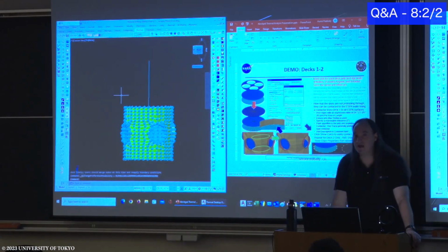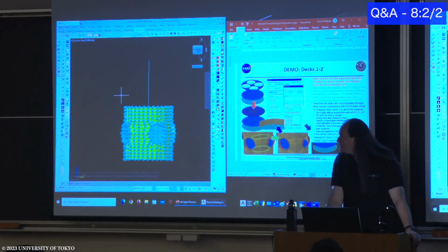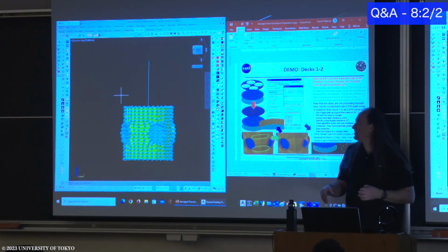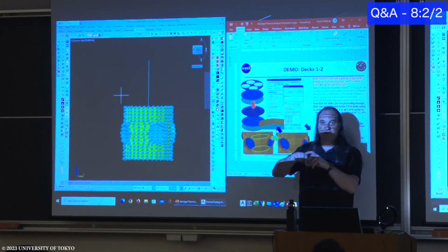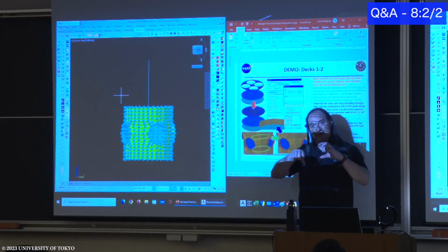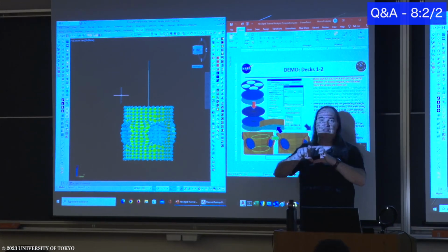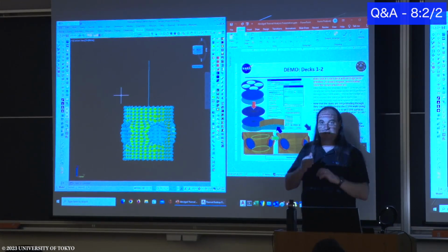And now you can see my mesh is much finer. But it's not going to give me options other than turn a quad into 4, turn a triangle into 4 triangles. That's it. It's not selective. And if I were to try to only do a portion of it, well, now I wind up with 3 nodes along an edge for one element and 2 nodes along an edge for the other element, and I've broken a link in there.